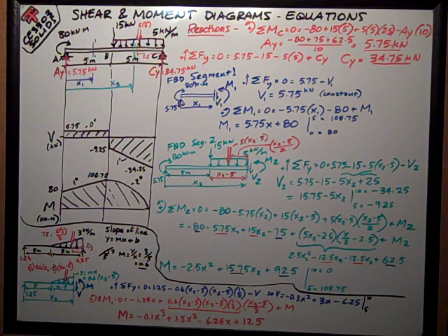Okay, if you thought that was bad, let's look at the moment. Doing some moments at this point. Simply negative 1.25x, because it's clockwise. Then I take this quantity, which is the resultant that I've put with the bracket under here. This resultant is 0.6 (x2 minus 5) times (x2 minus 5) times 1/2, because it's a triangle.